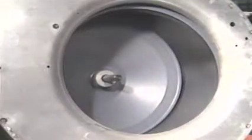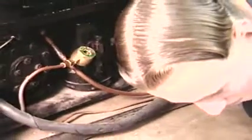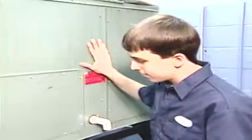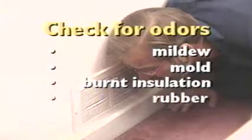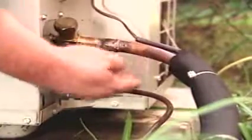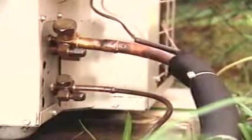With the system on, look for other symptoms, such as correct fan rotation. Listen for any abnormal sounds, such as hissing, which could indicate a leak in the sealed system, or squeaking, which could indicate a worn bearing. Check for abnormal odors, such as mildew, mold, burnt insulation or rubber, or leaking refrigerant. Carefully feel for the temperature of lines and components by patting. Temperatures can be hot enough to cause serious burns.